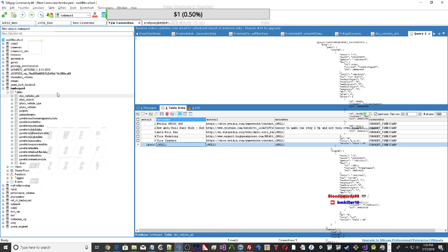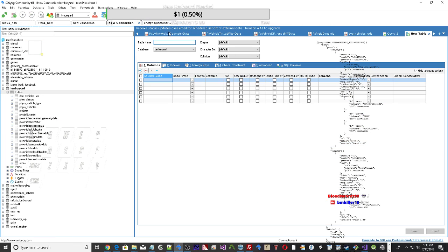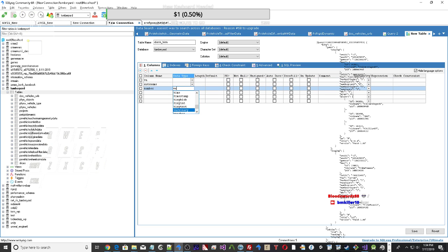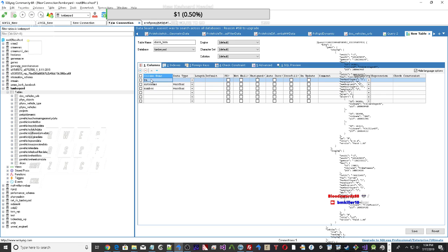Compute the mass supported by each suspension spring. PxF32 suspSprungMasses[PX_MAX_NB_WHEELS]. PxVehicleComputeSprungMasses(numWheels, wheelCenterActorOffsets, chassisOffset, chassisMass, 1, suspSprungMasses). Set the suspension data. for (PxU32 i = 0; i < numWheels; i++) {